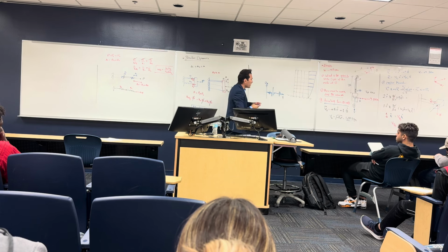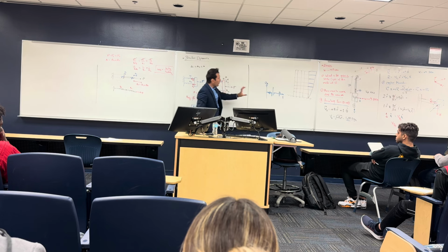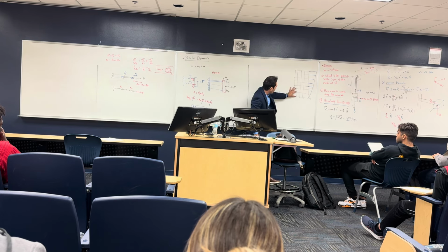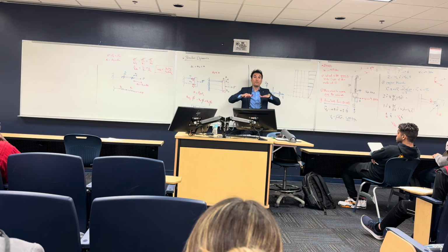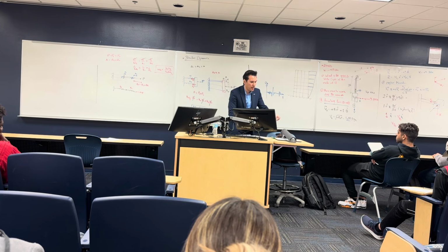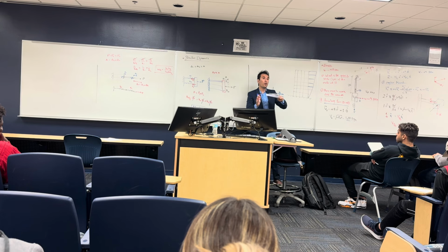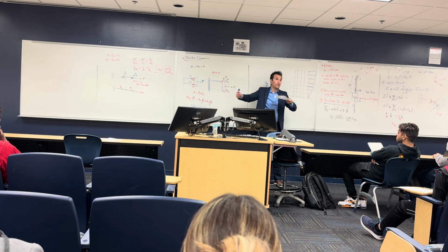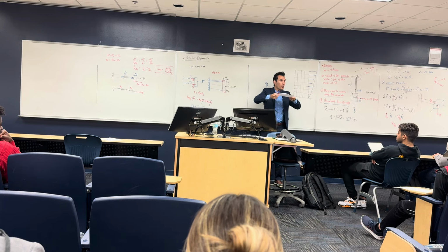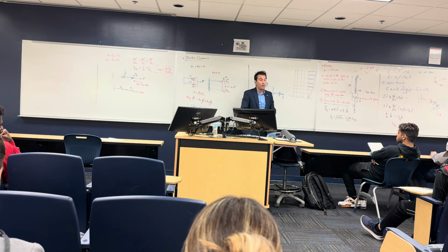But there's something that we can relate to what we did here. Look at the delta of this column and this column and this column. All these columns have the same delta. Why? Because they are attached to a very, very rigid slab. Let's say the slab is very rigid. If the slab is moving this way, it's going to take all the columns with it. It's not going to take 10 and leave 10. If we are all going to move this way or this way, we're not going to leave each other. So both of them have the same delta.